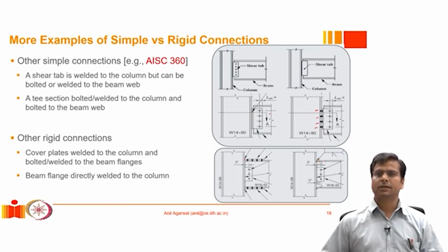So these welds are not really meant to transfer the shear force, and the shear force, which is anyway highest near the web or the centroid, that is the neutral axis, it is much more prudent to provide shear connection near the neutral axis of the beam in both cases.